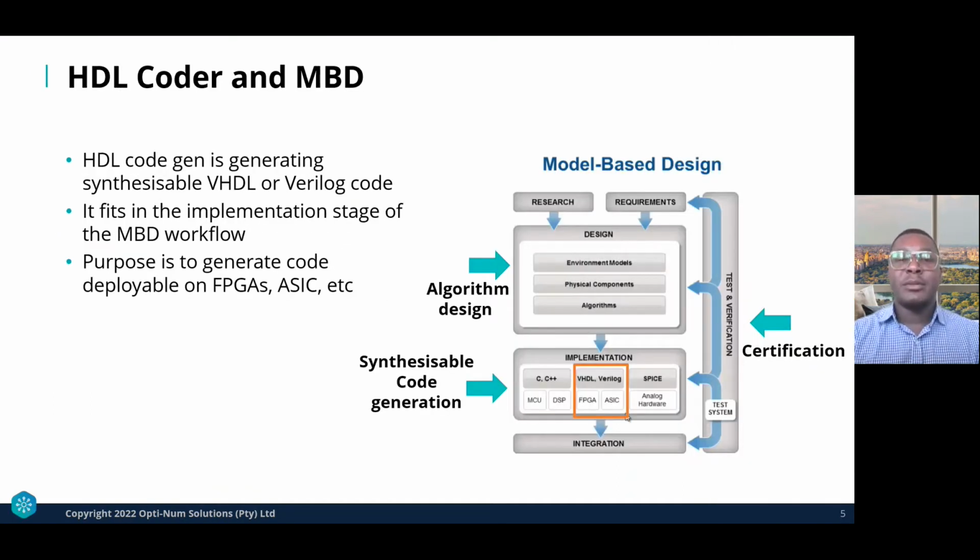HDL Coder and model-based design. HDL Coder is basically generating synthesizable VHDL or Verilog code, where synthesizing means that the HDL code is converted into a gate-level description of the circuit mapped to the target hardware. And HDL Coder fits in the implementation stage of our model-based design workflow.